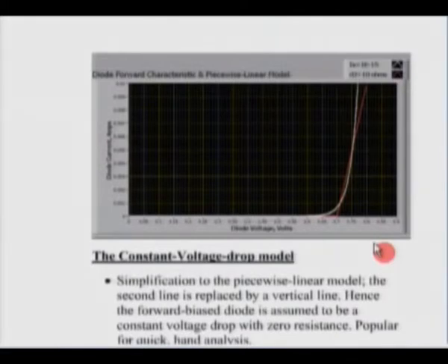Now in a lab, once you are able to get this IV characteristic, you could choose two currents on the y axis and, if you expand your CRO and make a proper reading, you could get the difference in the diode voltage there, and from that you can get a fairly good estimate of Rd. That is how you would measure. If you want to model it properly, that is how you do it in the lab.